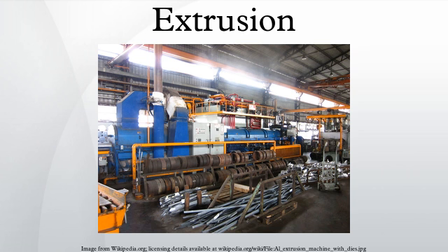Pipe, a flow pattern that draws the surface oxides and impurities to the center of the product. Such a pattern is often caused by high friction or cooling of the outer regions of the billet. Internal cracking, when the center of the extrusion develops cracks or voids. These cracks are attributed to a state of hydrostatic tensile stress at the center line in the deformation zone in the die.